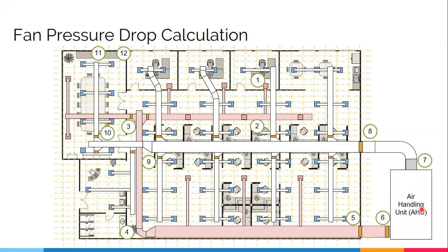When we get the pressure drop for the air handling unit, we typically take the longest run, or the farthest run, because usually the farthest run experiences the highest pressure drop in the system. For the pressure drop, we consider both the return and the supply duct.